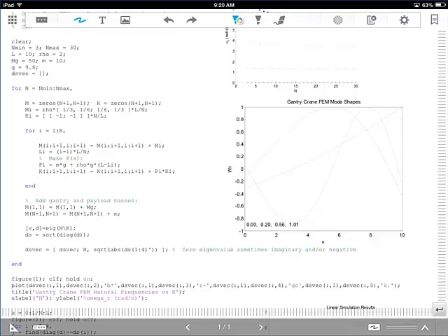So now we actually have pi inside the loop, cutting and pasting the element matrices in for the mass matrix and k matrix. Now this one depends on pi, and here's the equation for p of x. So you actually have to put it inside the loop that's generating these element matrices.